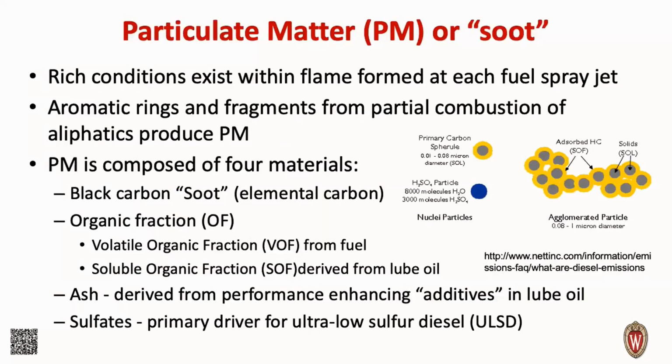So soot is really particularly interesting. Particulate matter, or soot, gets formed, as I just showed you, in the rich conditions within the flame from each fuel spray jet. So typically you have a 6-hole nozzle, so you have 6 of those plumes identically coming out across the chamber.